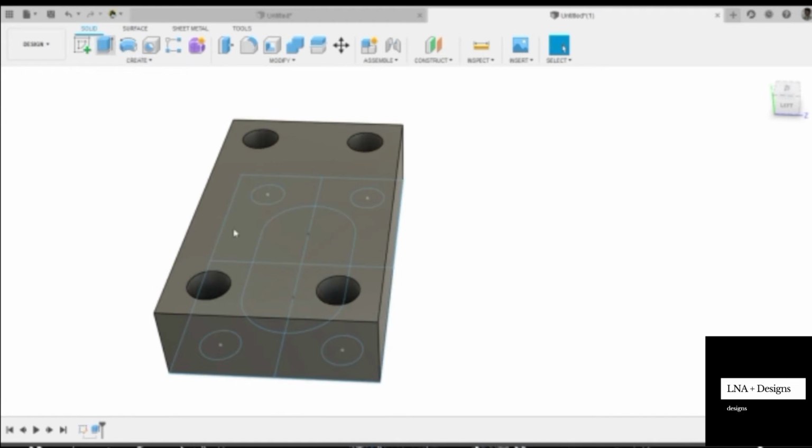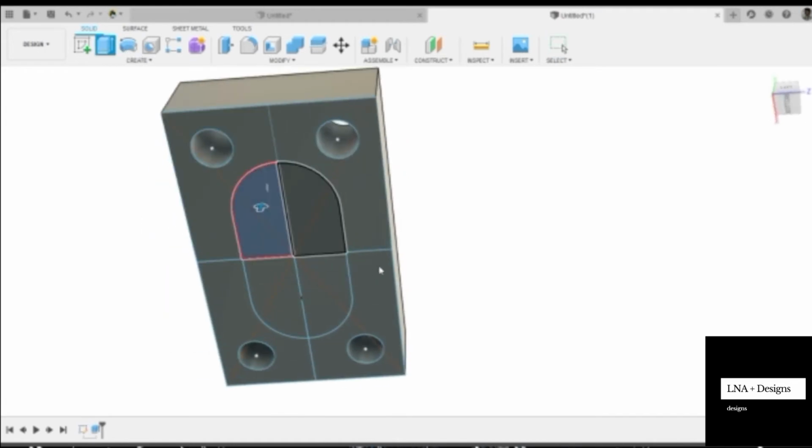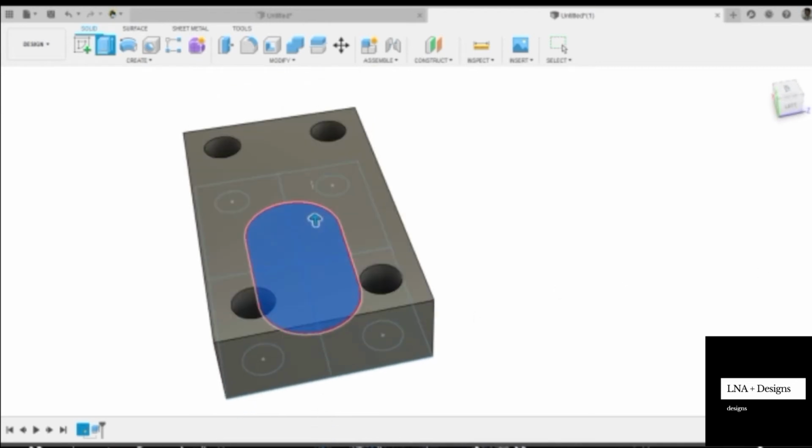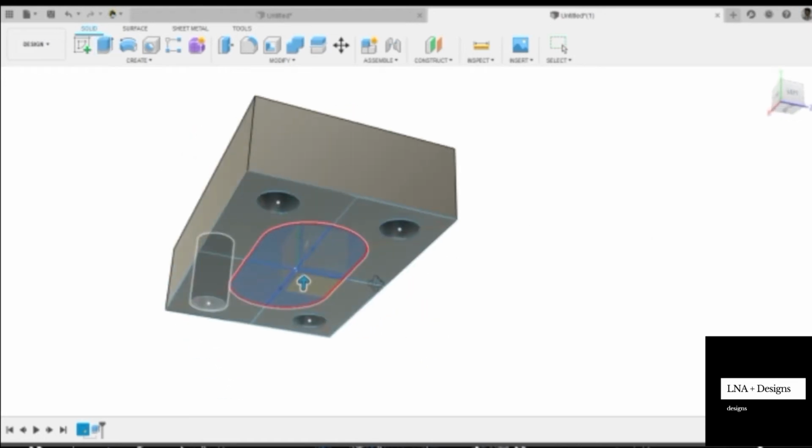And how do you bring this here? Not by move, it is by extrude. Just click it, boom, and go to the start. Start basically defines where this profile should start from, and just clicking from this object.